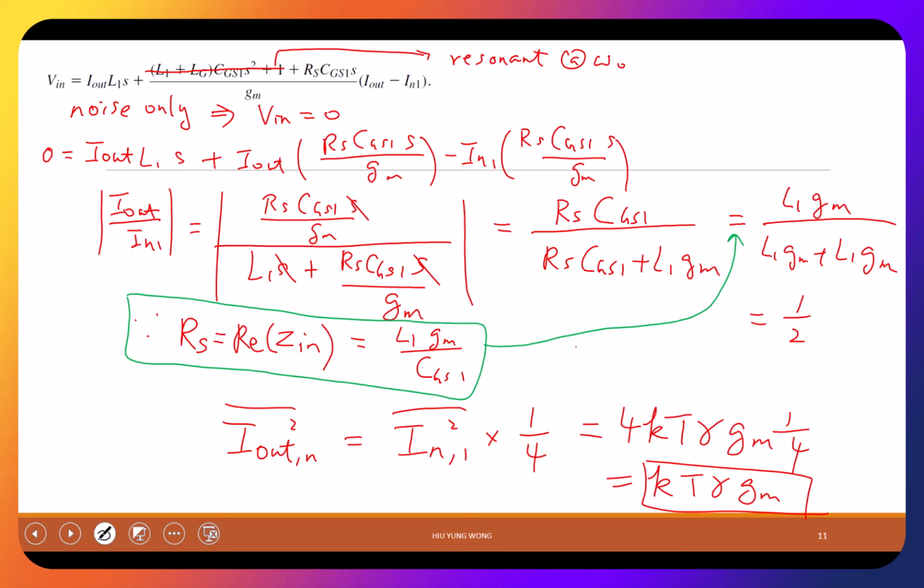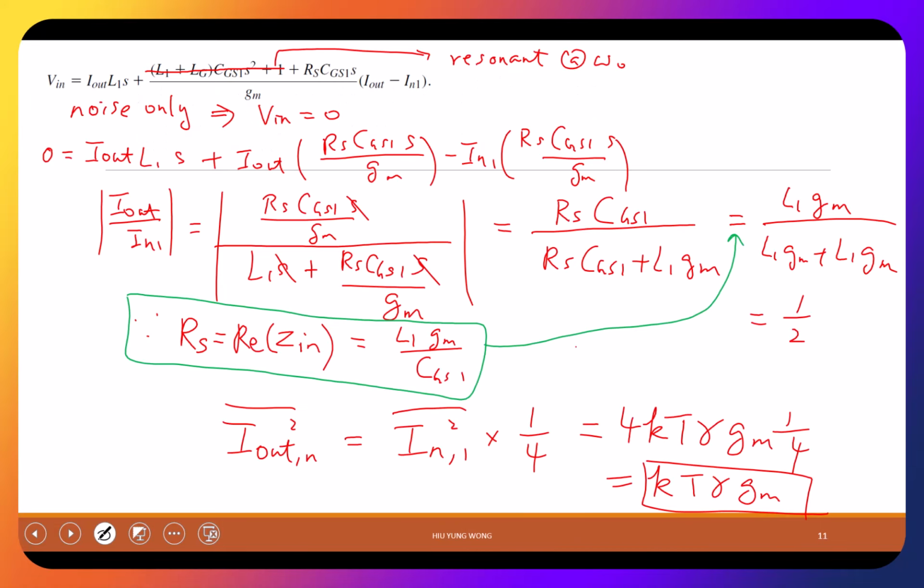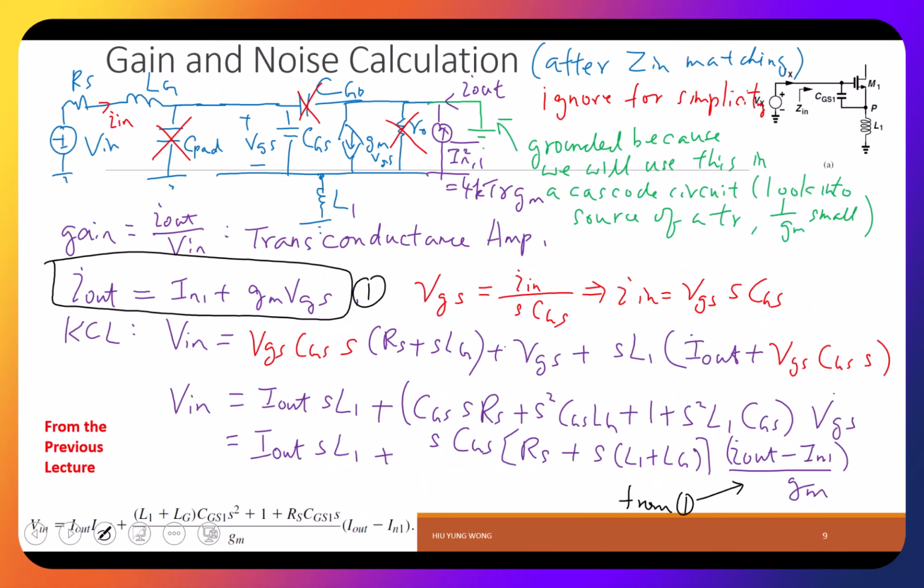Right, so we got the gain at the output. I mean, the whole circuit, we got the gain at the output. But now let me ask you one more time. Very good. He said this is just a common source, not a common source with Cascode. But one more important condition: we assume the output is grounded. Right?